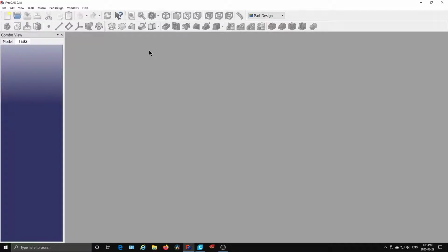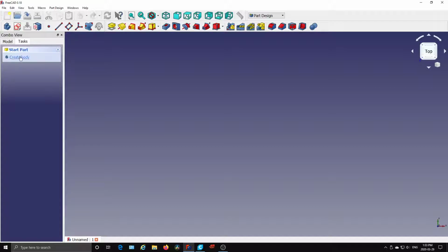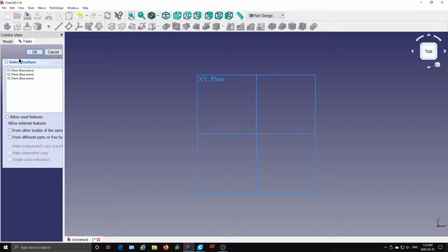Okay, I'm back. Now that you've seen the actual nuke entrances that I made, I've just fired up my FreeCAD here. I'm going to show you how I sketched them out. They're very simple. So I've got my FreeCAD set on Part Design. I'm going to create a new document, create a body, create a sketch, and I'm going to select the XY plane base and click OK.